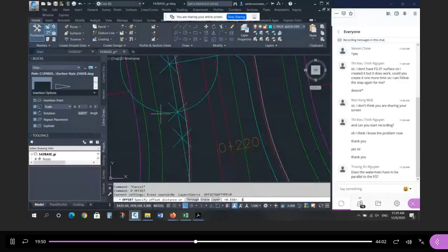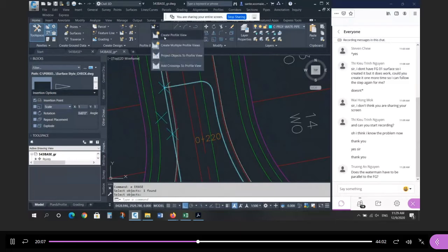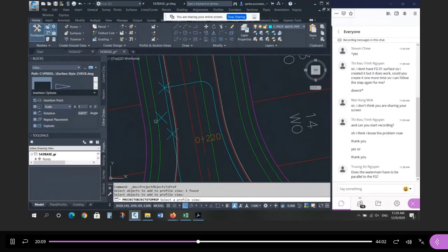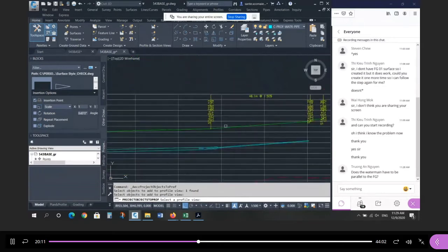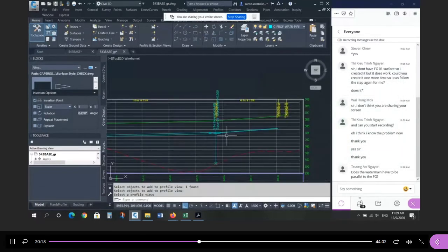So if I'm going to offset 3.3, take this and go perpendicular, that's where the actual hydrant position will be in section, right? But it's projected to the same station in the center line. So if I was drawing the hydrant, that's where it would be. But I didn't change the station, I just moved it in section. So we do this again. This is where the hydrant goes. We can draw that position here. Again, bring it into range. And that's where the hydrant goes.